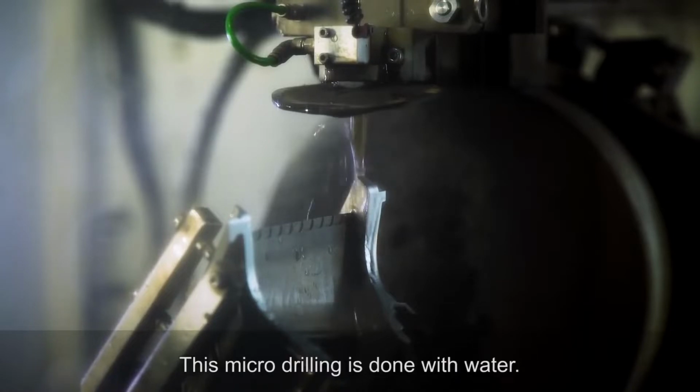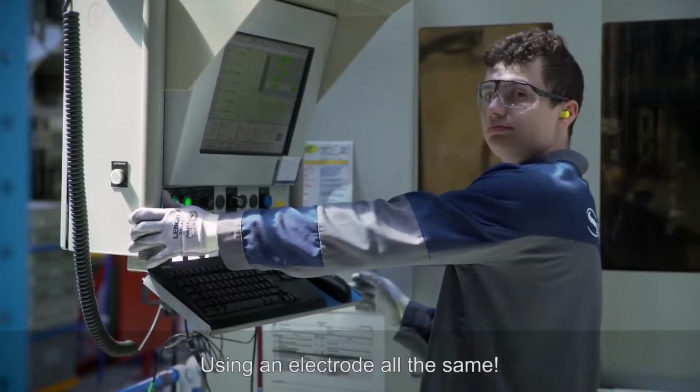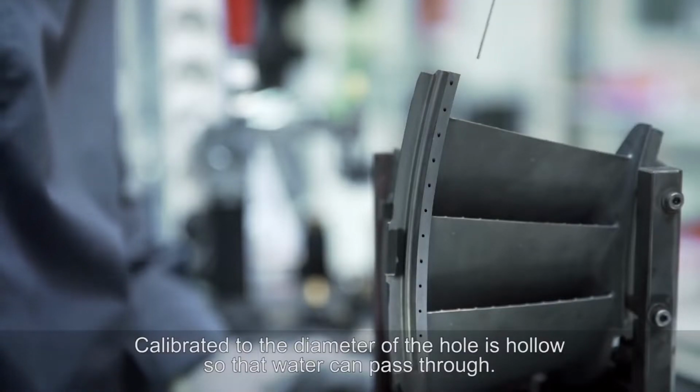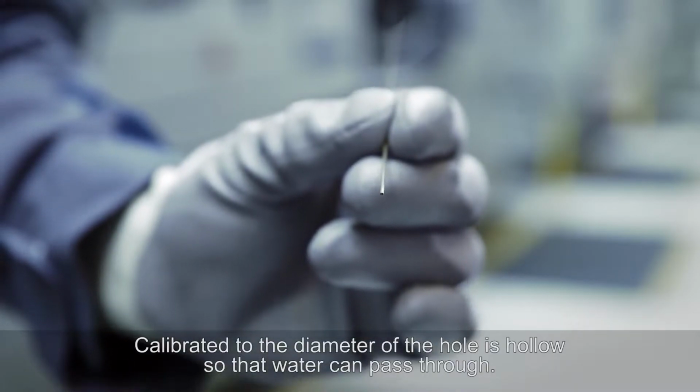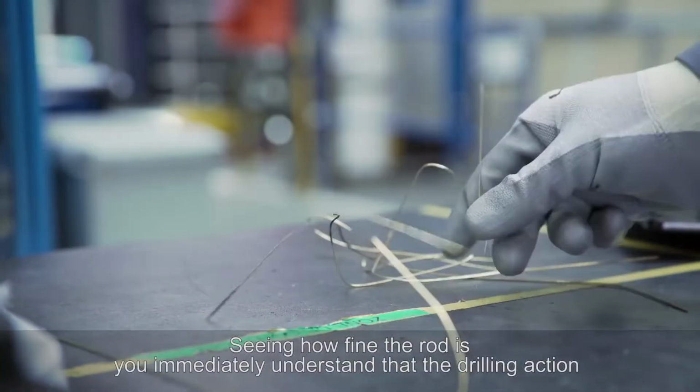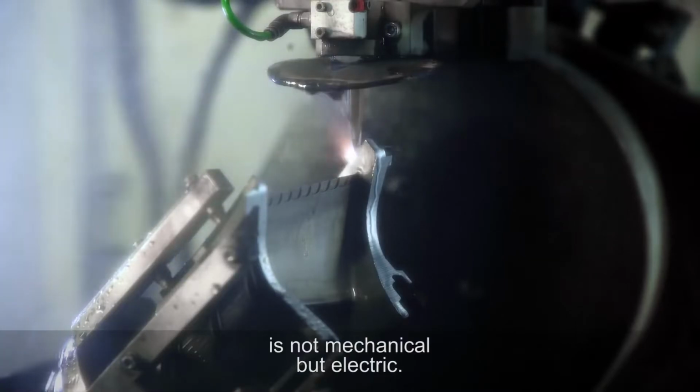This micro-drilling is done with water. Using an electrode all the same, calibrated to the diameter of the hole, is hollow so that water can pass through. Seeing how fine the rod is, you immediately understand that the drilling action is not mechanical, but electric.